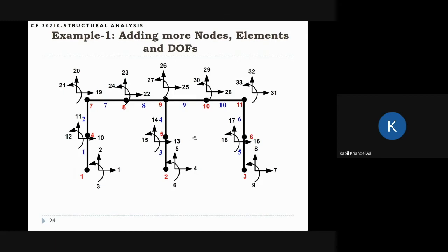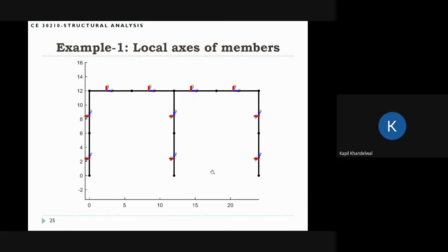Okay, so in this case there will be no load acting at the midspan of the member. Still, these 9 and 10 elements will have Q, acting vertically downwards. So there are distributed loads on members 9 and 10, but there are no concentrated forces acting at the midspan of any of the members. This is an important difference, and you have to be careful when inputting the data. But if we input the data correctly, it turns out that we should still be able to solve it.